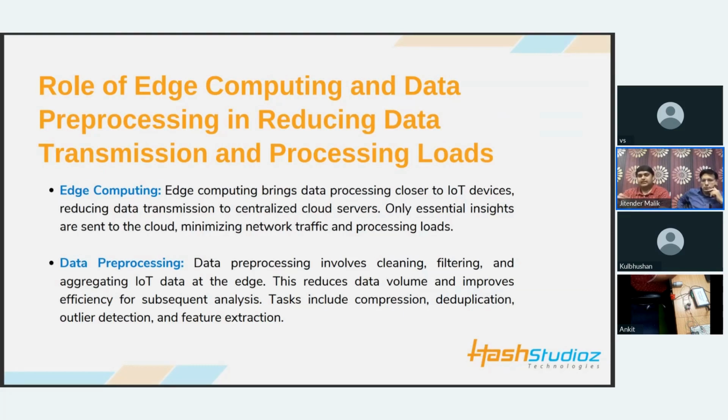So we choose the frequency of sampling and the resonant frequency of the sensor in such a way that our application scenario is completely fulfilled, and we are capturing the exact data and investing the exact cost. Because the higher the sensitivity of the analog sensor, the higher the cost associated with it. And in industrial spaces, these costs may go up significantly because the component has to be temperature safe and environment safe, right?